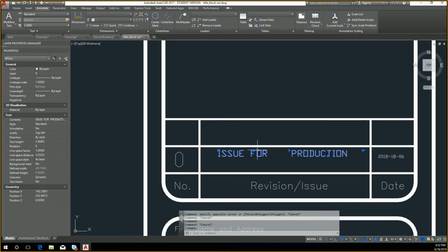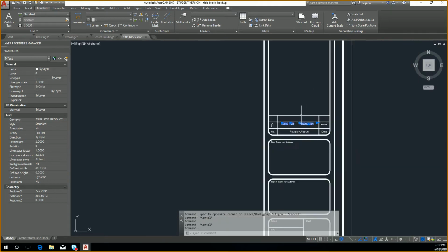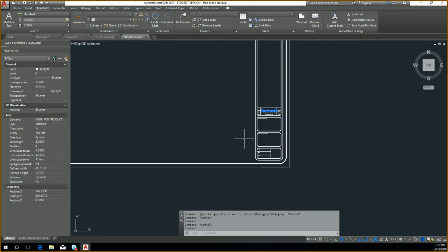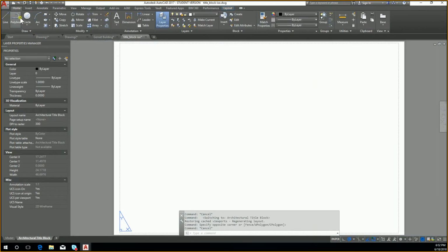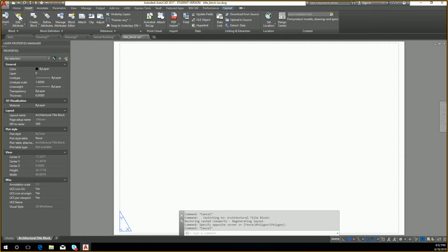So this is not a very dynamic system. It is something that just is manually edited within AutoCAD at least. There are other programs that do actually have, and some actually versions of AutoCAD, they have a system where the revisions are linked a little bit more intelligently. So there's ways to roll up your revision and actually have it shown across all your drawing packages. So as we mentioned, when you're in layouts, this is typically where your actual drawing package would be.